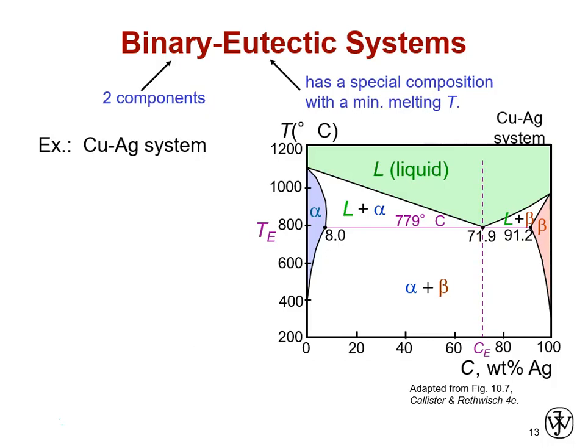This is one of the multiple spontaneous thermodynamic phase transformations that we get in materials. These happen in all materials, but they're most noteworthy and plentiful in metal systems. Because we have two components, this is called a binary eutectic. And we're going to use copper-silver for this. It's a famous one, and nice and non-toxic, unlike lead-tin. So on our diagram we have 100% copper on the left and 100% silver on the right. So we're going to use some animated examples to walk our way around the phase diagram.